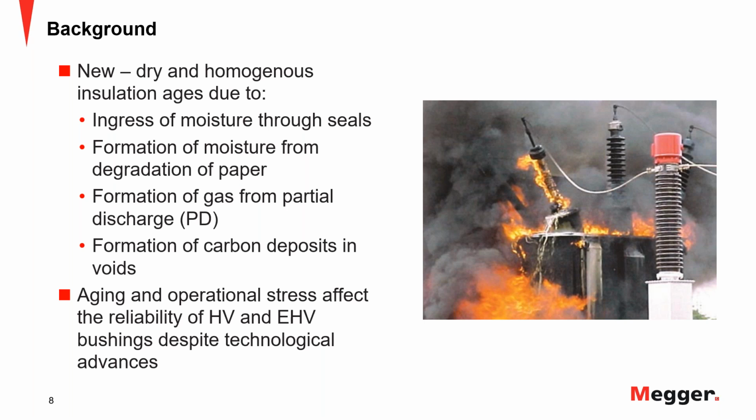insulation system. Keep in mind that like any organic material, paper and oil that is inside these bushings tends to age. So aging is a one direction process, right? And we need to understand that aging is not only because of thermal effects, it's because of the normal operation that we have. It's because it's working at high voltage and extra high voltage stresses.